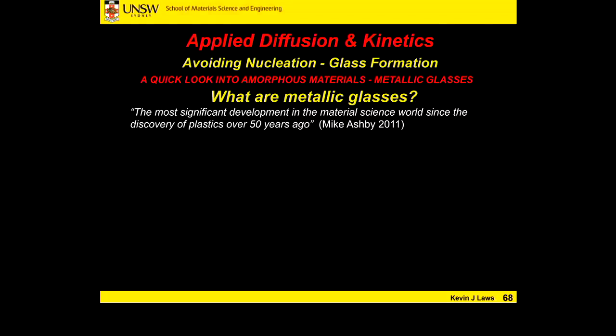If we make a material that's amorphous, we still have these magnetic moments of these elements, but we don't have this crystal order anymore. It's amorphous. It's not quite random, but it's definitely not crystalline. By having the dispersion of these magnetic moments throughout the material, we can get extremely good soft magnetic properties. And these are used in transformer cores. They have been used in transformer cores since about the 60s because they are the softest magnetic materials known.